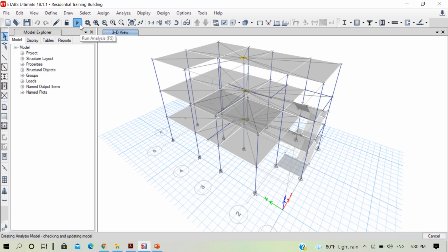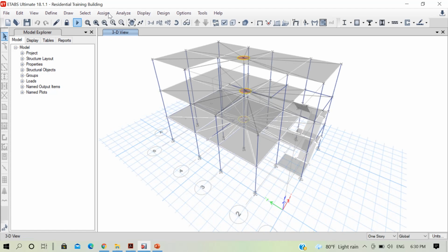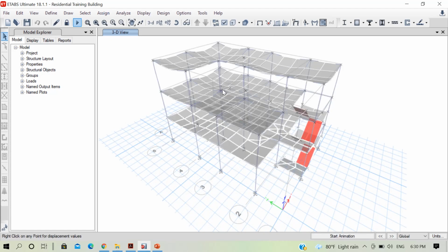Depending on the complexity of our structure, the analysis time taken may be long or short. We saw different kinds of solvers present in ETABS under the options in the Analyze menu. We had three different types of solvers there, each suitable for particular conditions, and based on the complexity of your model, you can choose a different solver. So this is our deflected shape. We saw some basic checks. Now first we will see some modal results in our ETABS model.